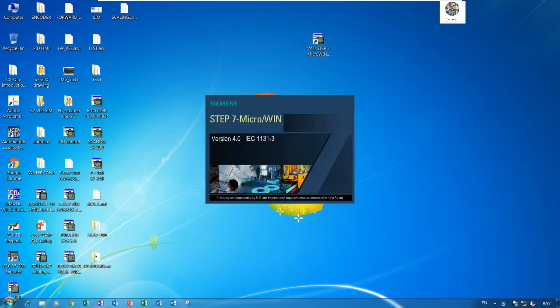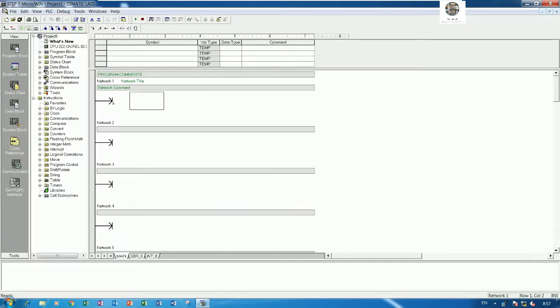First let's open the PLC S7-200 schematic in STEP 7 MicroWIN. And we will get the data from PLC S7, sorry, PLC GE, right? So we will start from V0. For example, I will turn on Q0.0, and this one we can command to get data from PLC GE bit 0.